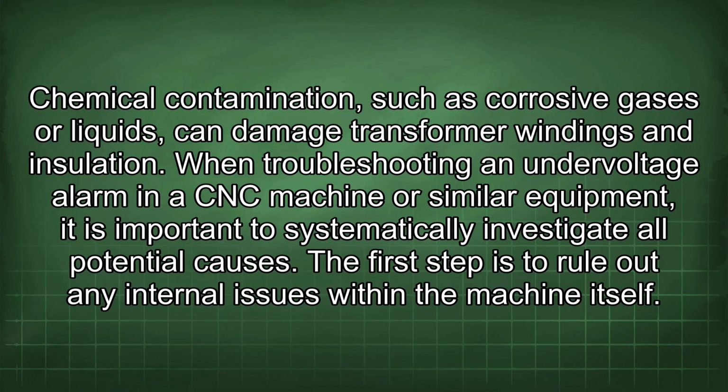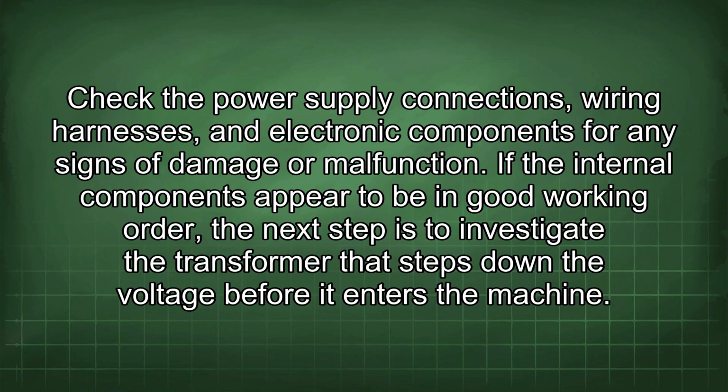When troubleshooting an undervoltage alarm in a CNC machine or similar equipment, it is important to systematically investigate all potential causes. The first step is to rule out any internal issues within the machine itself. Check the power supply connections, wiring harnesses, and electronic components for any signs of damage or malfunction.